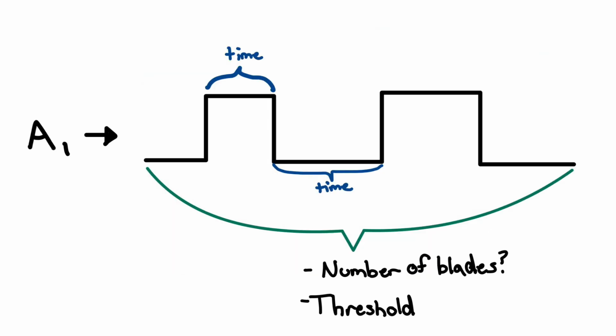So how do we take our analog signal and convert that to revolutions per minute? So we first have our analog input. We find that thresholds, and we look for rising edges, or when, in my case, the fan blade is blocking the photodiode. We then find the differential between rising edges, and we divide that by the number of blades, and we can figure out the RPM.